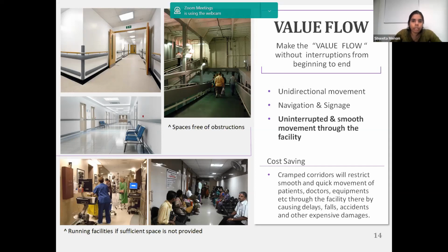You've given a corridor, it's got a good width, you've given a ramp, it's got the right dimensions and slope. Make sure it's clear, make sure it's neat, make sure the floor is anti-slip type floor where you get the grip as you walk down. Make sure there are handrails. Staircases also need handrails on both sides in hospitals. So make sure all those necessary elements are provided just to avoid a future much bigger expensive damage happening.